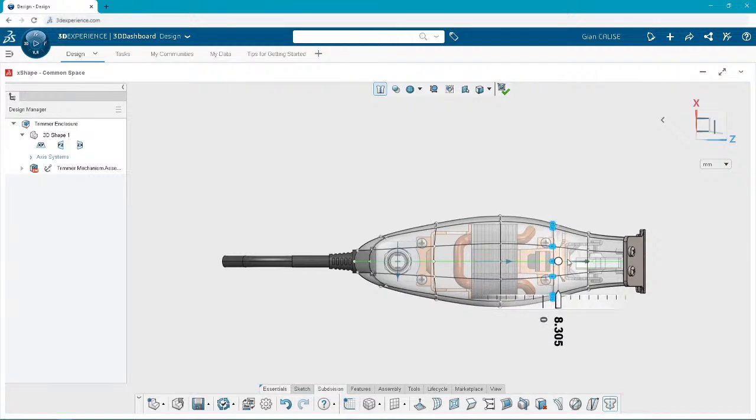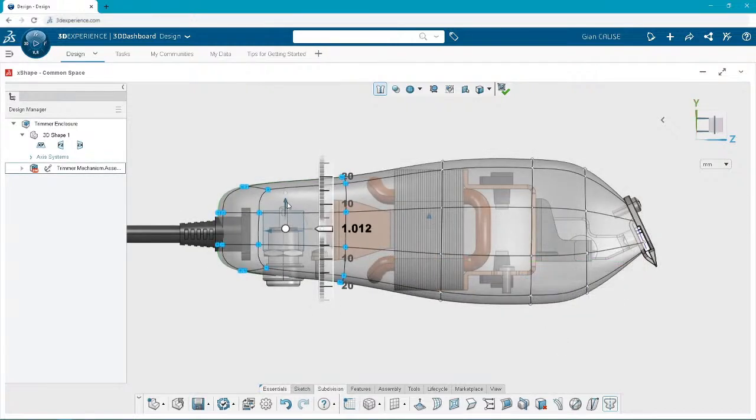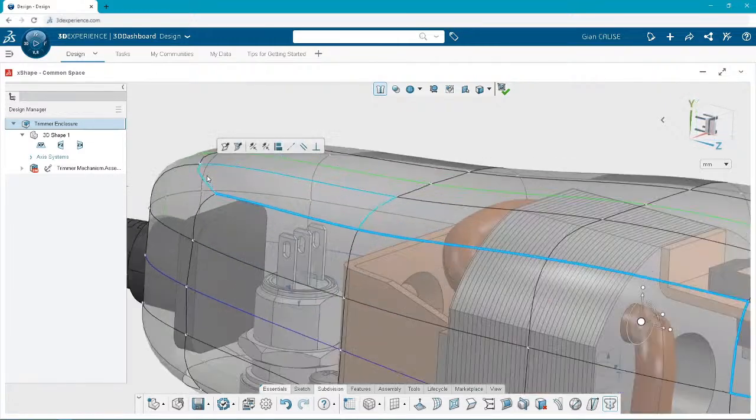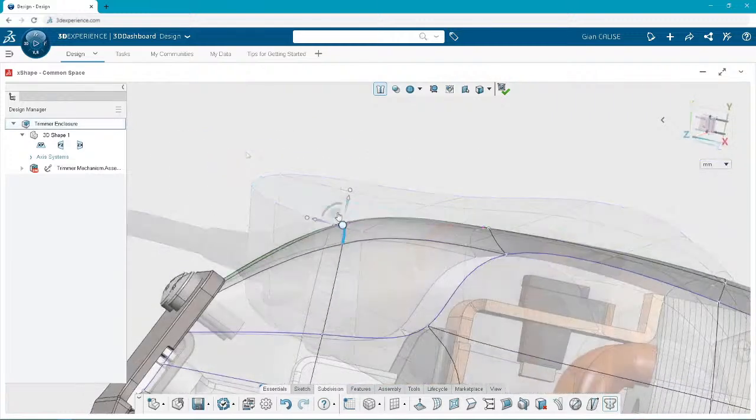we're looking for. So as we continue along here, I know that I'm going to need a parting line around this. This is going to be an injection molded part, and we're not going to do everything to prep it for injection molding, but we want to be smart about how we model this thing so that when the time comes, most of our work is already done. So that's why I'm going to add a crease around this whole side of the model so that we can get the draft that we're looking for, but you'll see more on that later.